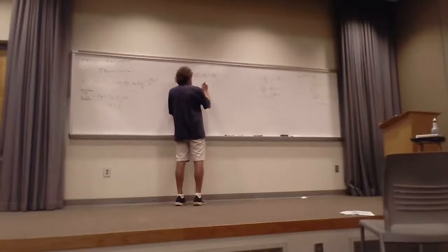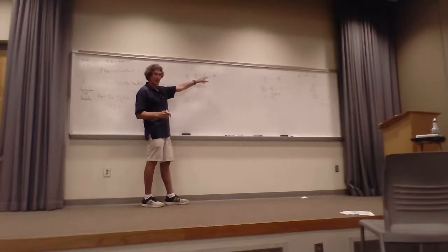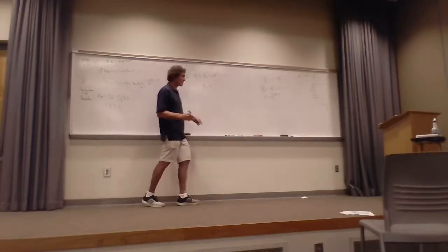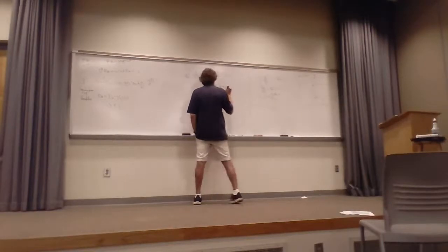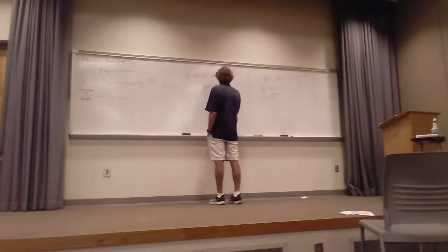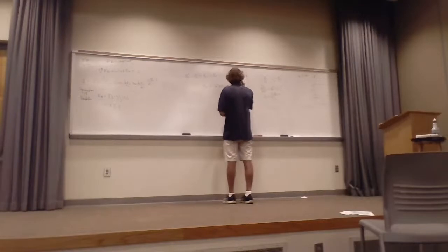So I can say that beta z, and just follow me on this, I'm going to take beta z to the other side. So I've got beta unguided squared here, which I'm going to write down as omega squared mu epsilon. That's beta unguided. And then it's going to be minus beta x, and beta x is m pi over a squared, minus beta y, which is n pi over b squared.